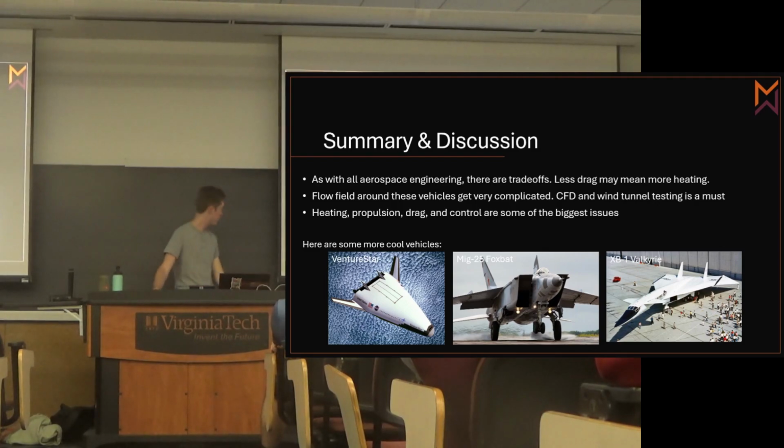But when you build a tunnel and you have it expand, so I have really high pressure in here, high pressure, and I get hypersonic flow in here, it's going to expand. But as it expands, you actually lose temperature. So my temperature goes down, and my pressure goes down, but my speed goes up. And you get issues.